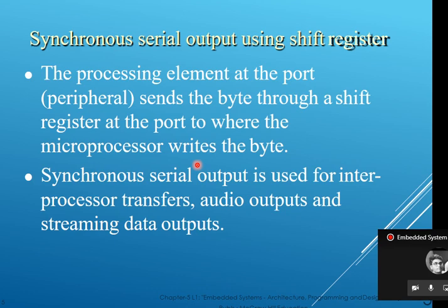So what it will do: suppose it is a 4-bit shift register, 4 flip-flops will be connected together, and at the first clock pulse, the first flip-flop will generate the output. Okay, and at the second clock pulse, that output from the first one will move to the second flip-flop, and similarly it will take another bit from the input. Let me draw.